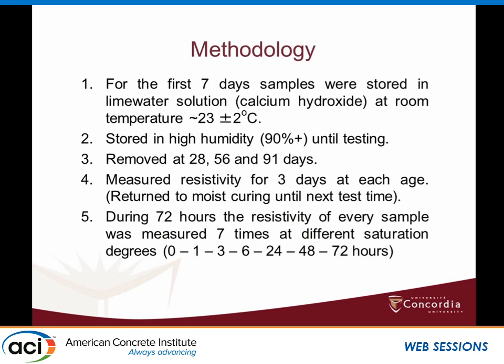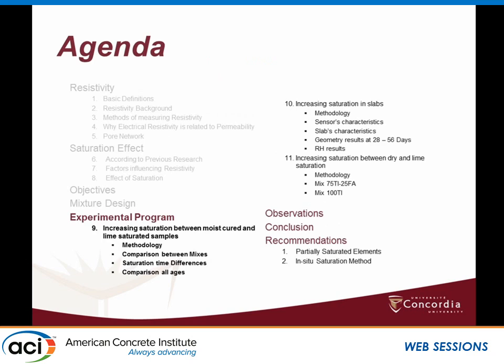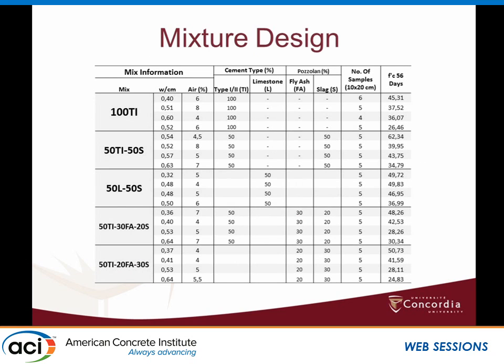The experimental program was that we cast all these 100 cylinders with different mixes. Also, I forgot to mention, you can see the water cement ratios, we start with the designs at 0.4, 0.5, and 0.6.